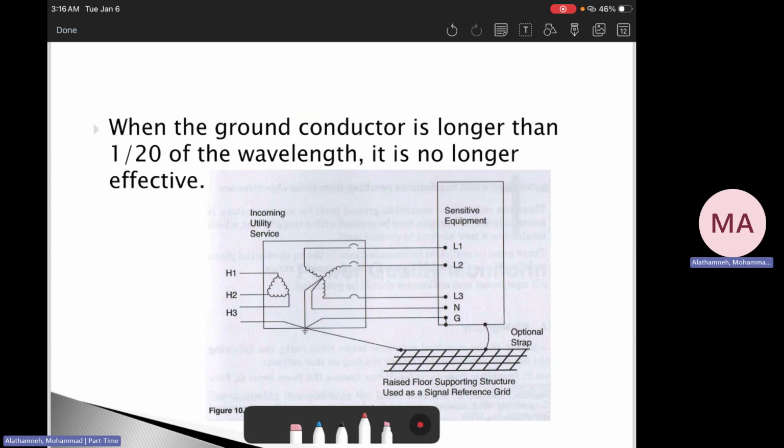The device ground bounces and can get errors. So if you have a control cabinet and a drive cabinet connected by a long grounded conductor, noise can still appear. But we need to consider local bonding, wide copper straps, mesh ground plane, and short connections. This is why electromagnetic compatibility engineers, we call them EMC engineers, love wide straps, because they have lower inductance. Then we need to make sure the ground conductor is not longer than 1/20th of the wavelength because, again, here we are considering this as a transmission line.